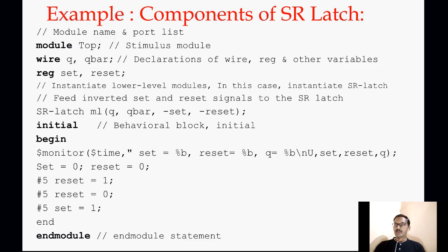Then register set or reset. When we specify it as reg, that is register. reg is a keyword. So when we specify this as a register, the set and reset values will be stored for all the simulation time. Then initial means the simulation will be started. Initial is nothing but a behavioral statement. Then begin means simulation started.